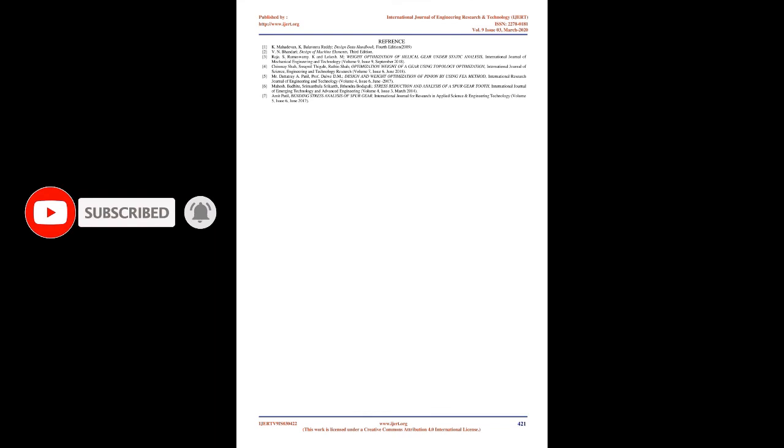Gear designing. For the gear model, we take a standard spur gear from SOLIDWORKS Toolbox. Assign the module and teeth number. The software will generate a gear using global equations. We optimize it according to design using static simulation. For simulation, the center hub is a fixed fixture and tangential force is applied on the teeth for the worst condition possible. Simulation of gear on SOLIDWORKS, Fig 2, 3.